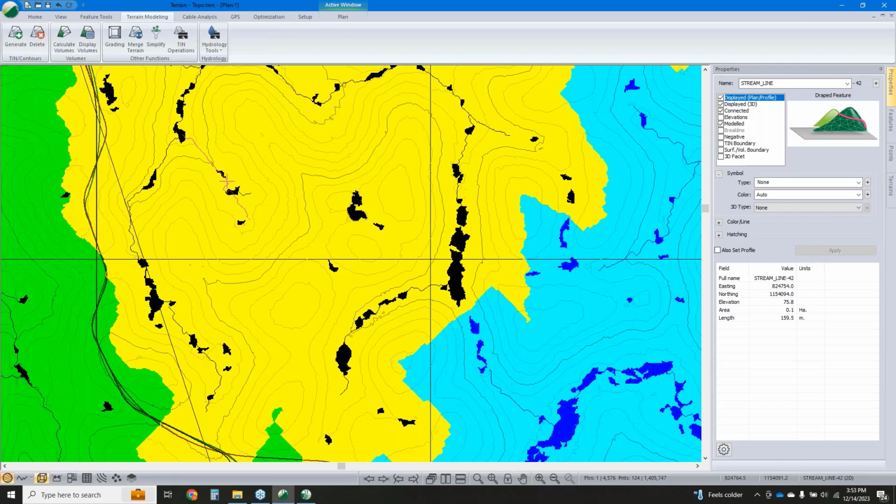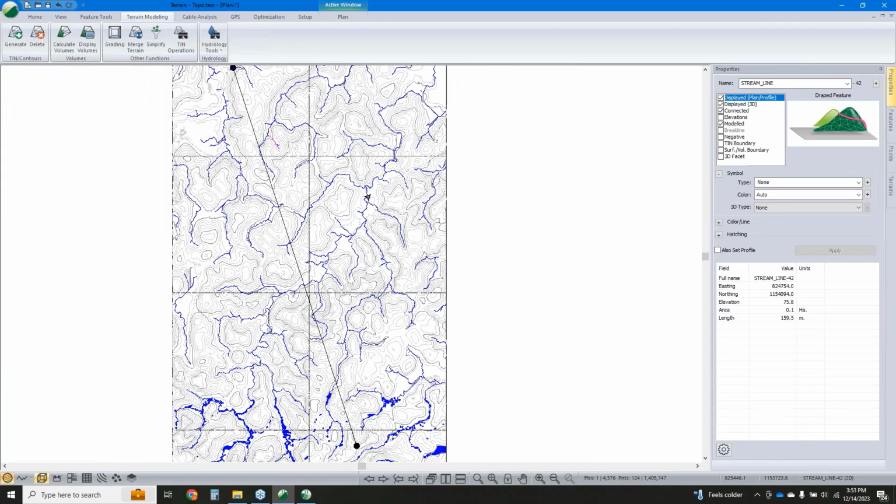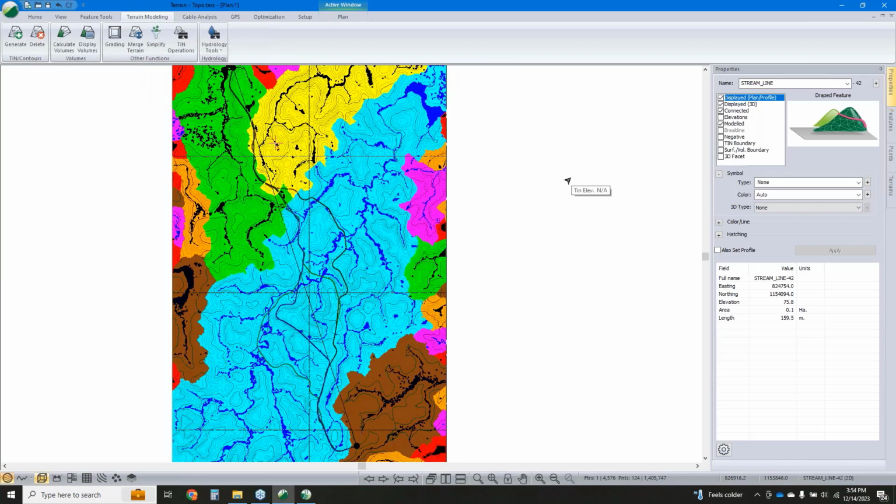Talking a little bit more about Path Explorer and no-go polygons, would you use the no-go polygon to keep it from paralleling a creek in a stream buffer? I wouldn't use a no-go polygon because the no-go is absolute. So I would use a polygon with an increased cost if you were having a problem with that. So that'll let it cross the creek, but it'll deter it. Again, I think if you leave it unconstrained, it'll generally produce favorable results without even adding an extra riparian buffer in there.